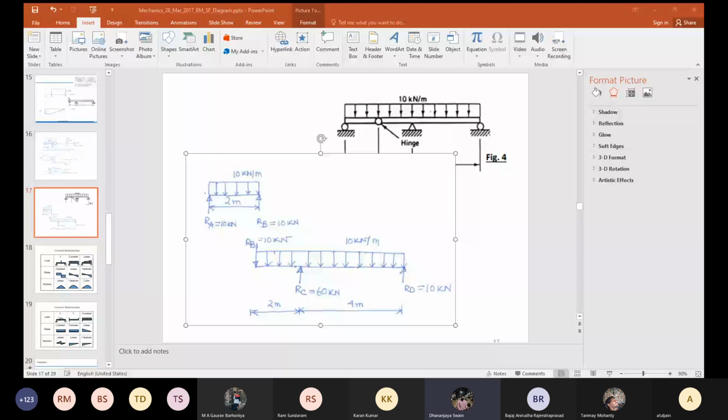You can write as many equations as you like. You can write an infinite number of equations, but we are not looking for the number of equations. We are looking for the number of independent equations. This is a case of 2D equilibrium. All the forces are aligned in the same direction. You cannot have more than two independent equations of equilibrium. Okay.